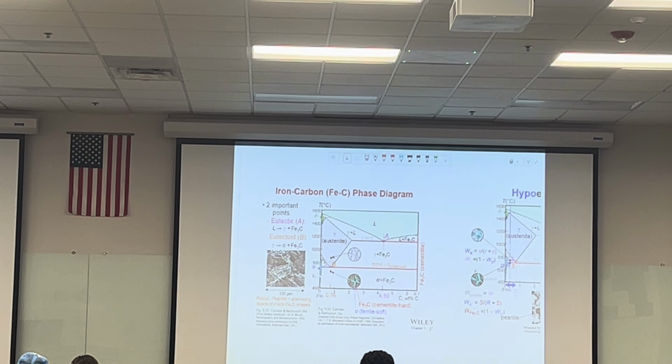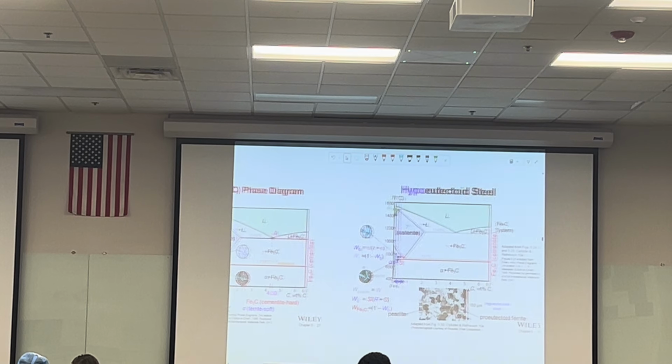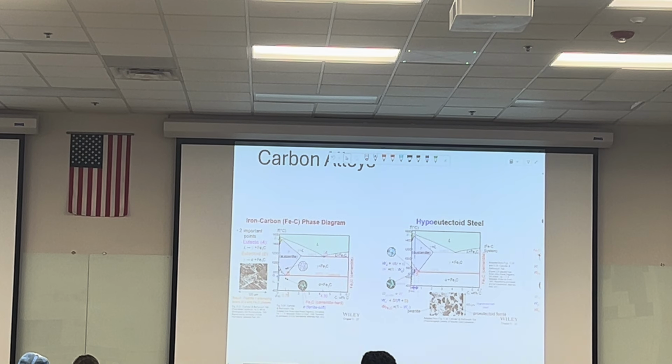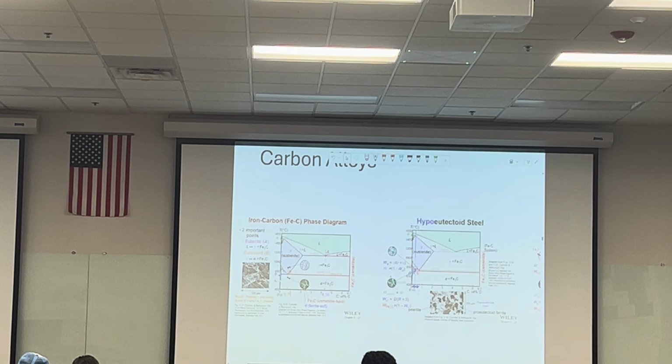So it's here. I'm assuming this thing is here. This lamella structure, that's the eutectoid structure. These blue lines are like the eutectoid alpha, but the pro-eutectoid alpha is this thicker blue.